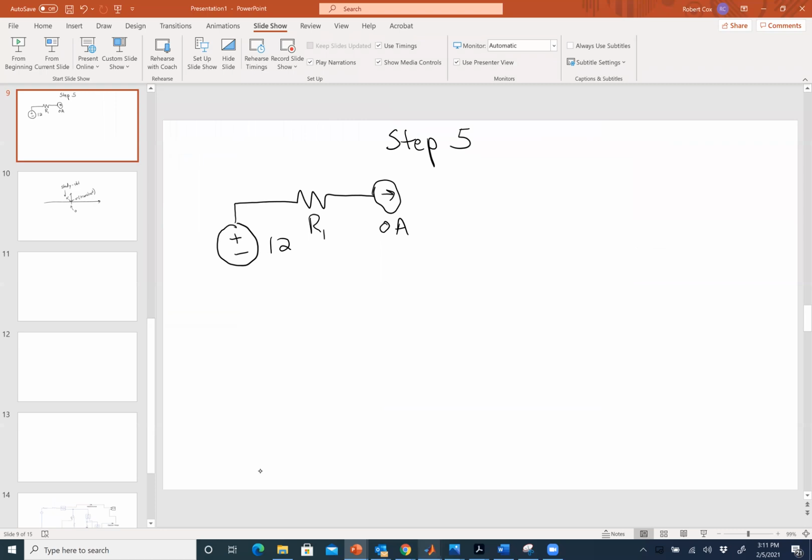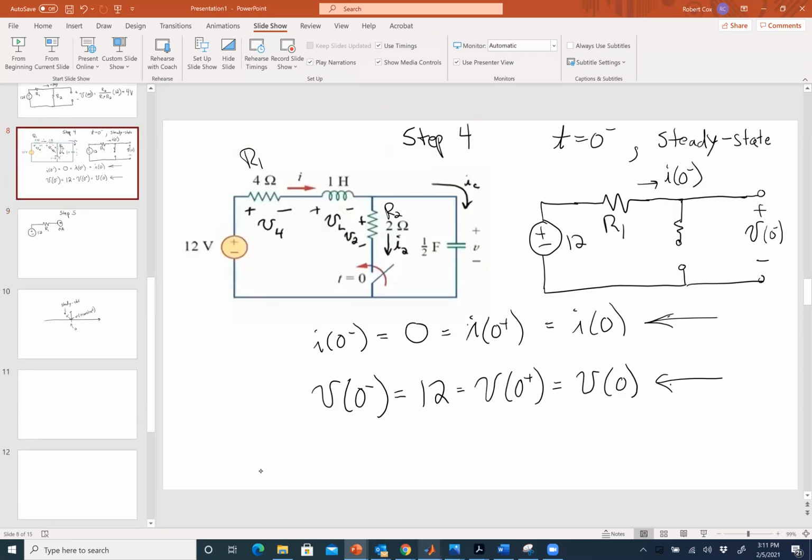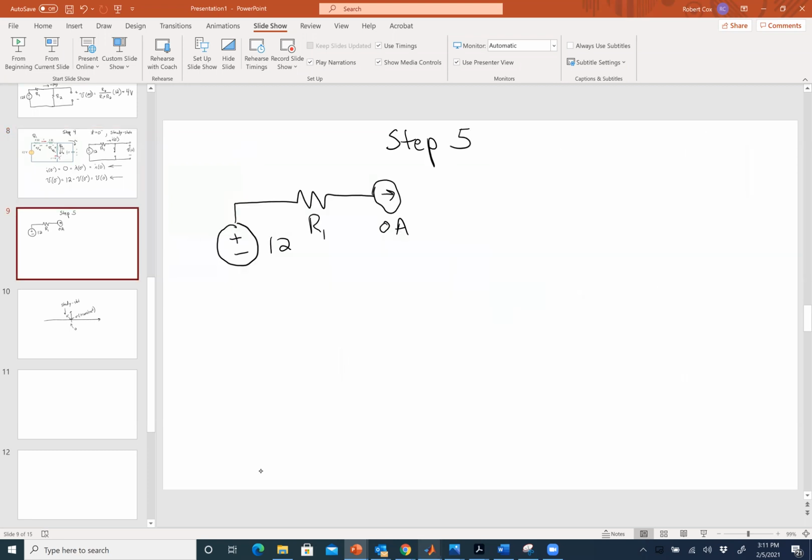All right. So, back to the circuit idea here. Essentially the inductor current's constrained, the capacitor voltage is constrained. So we make those replacements. I replace the inductor with a current source. I make sure that when I draw the circuit, the switch is closed. Okay. Now, what do I do about the capacitor here? Voltage source.